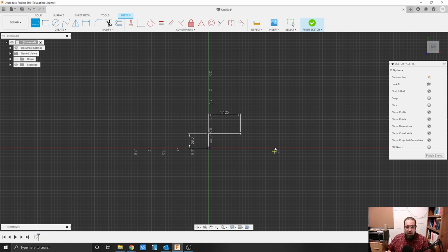Okay. Now that I have those two lines drawn, I can draw down, and you'll see if I hover over this, you'll see that green line there. It helps lock in that distance. It's what's known as a projection line, meaning that it's lining up with that origin point, and it's going to make sure to stay in perpendicularity to it. Okay, you can also see on there that this corner right here, as long as I hold it at that 90, we see that 90-degree identifier up in that upper right hand corner of our object too.